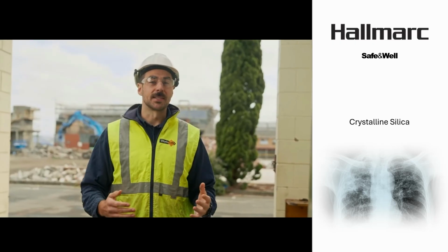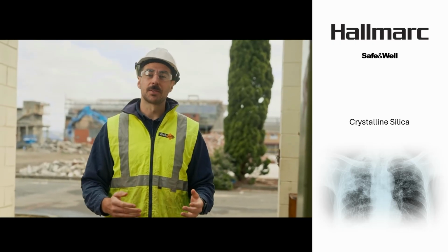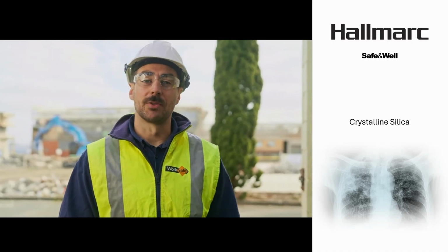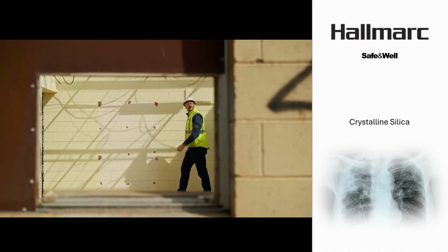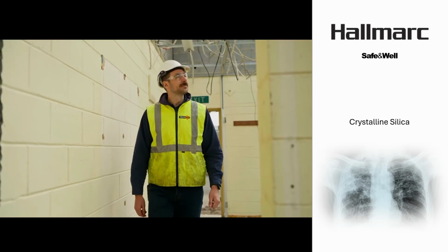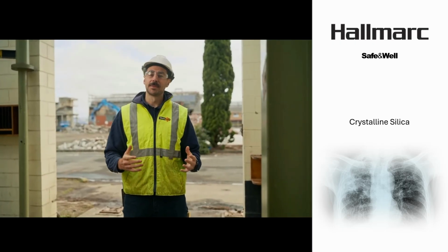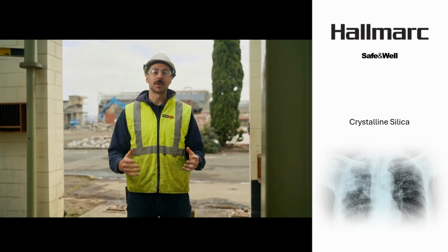Large ventilation systems like air scrubbers can be used to remove dust from the air. These systems work best when paired with other controls. Air scrubbers are great for enclosed or partially enclosed work areas, where silica dust can build up. When setting up and maintaining these systems, consider the airflows and direction.